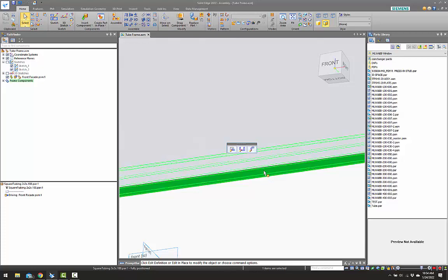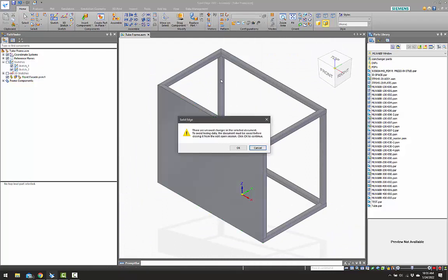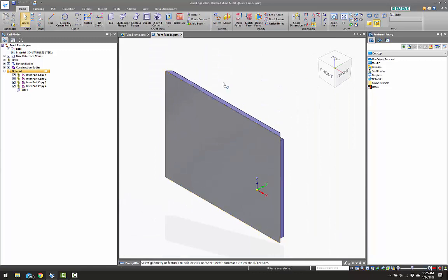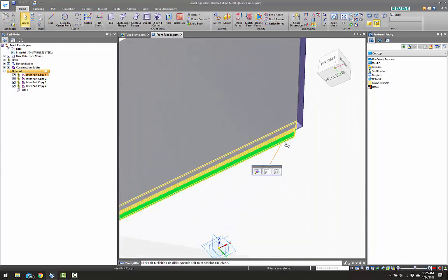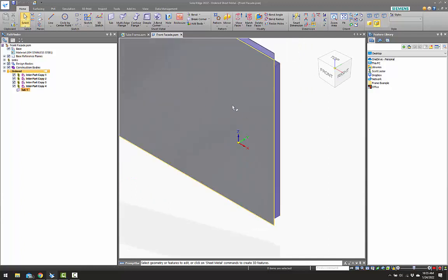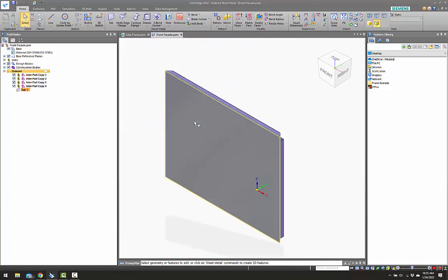If I go change this, then when I open this part, I'm not going to do it just right now. I will here later in the video. But if I go change this part, which, as you know, we used the face as a plane and we use the edge as a coincident sketchmate, then we may end up with errors over here, on our tab, saying that geometry has been lost.